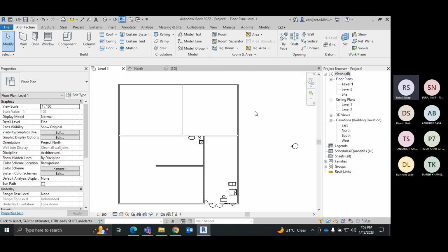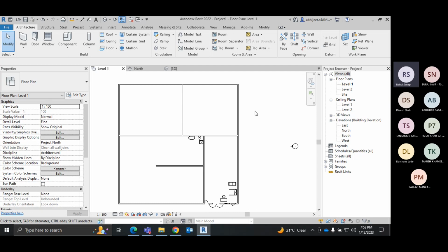Okay. So I'll assume that I'm only putting a slab over there, only concrete slab, because again there are two different methods. In the wall placement, we considered the middle layer as a brick layer, then two outer layers like external plaster, internal plaster, then a paint layer. So about 4 to 5 layers we have considered. If you want to consider the same layer structure in your floor or in your roof, you can do that. But if you want to place tiles as a separate part, that also you can do. It totally depends on you.